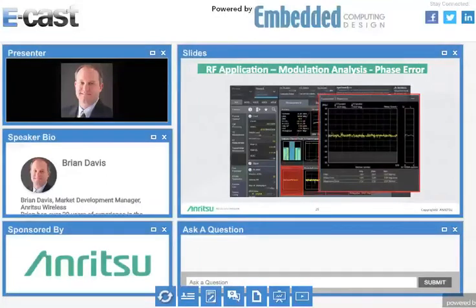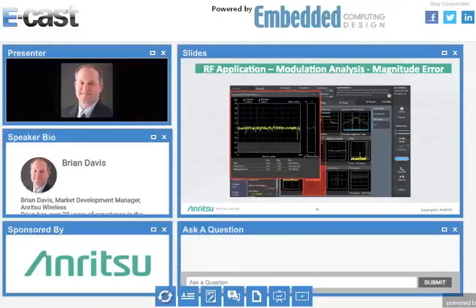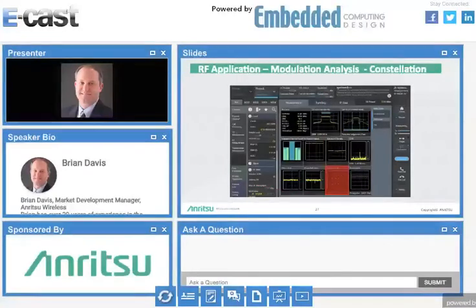Phase error. So this will give you information related to EVM, but just looking at phase, looking at your oscillator accuracy or deviation from the ideal signal. It's not looking at the time domain, but the degree of error per symbol. You could also call it jitter in the frequency domain. So here we're looking at the degree of the error in root mean square over the demodulated signals, so it's 0 to 600. Magnitude error, this is the percent of magnitude in root mean square over the demodulated symbols. So in the demodulated reference signal there in a percentage.